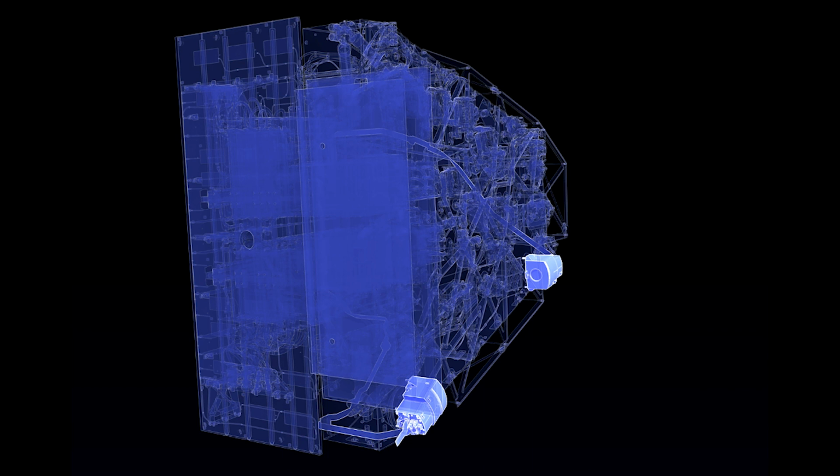They can bend and flex according to commands from the wavefront sensing and control system to correct for any small imperfections in the surface of other mirrors in the telescope or instruments. Each mirror is only about 2 inches, about 5 centimeters, across, yet has more than 1600 independent actuators to adjust its surface. Every actuator is independently commanded with a precision better than 62 picometers, less than the diameter of a helium atom.